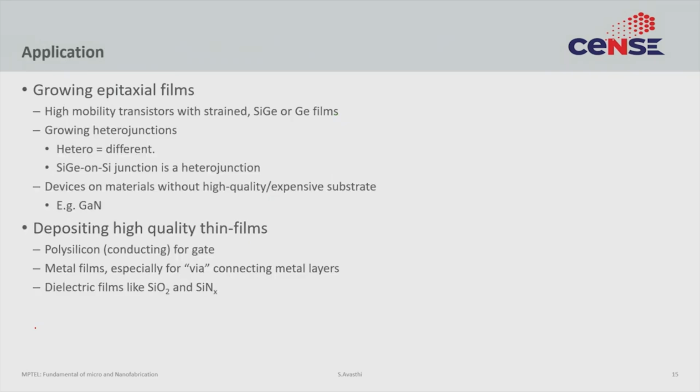In general, CVD is used to deposit very high quality film. Chemical vapor deposition films have very low contamination, can often be epitaxial or crystalline, often single crystalline, and all of these advantages mean that they are perfect to grow device grade semiconducting material.